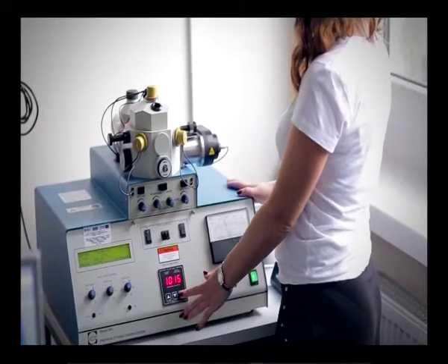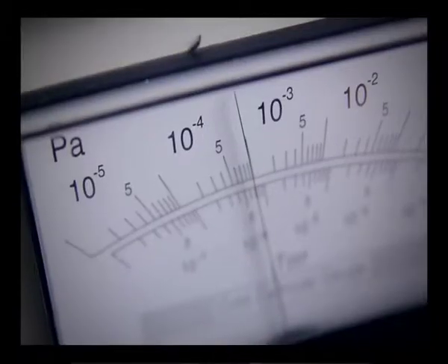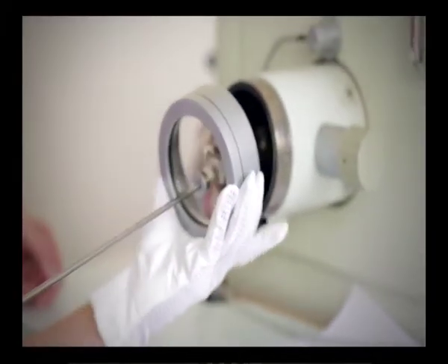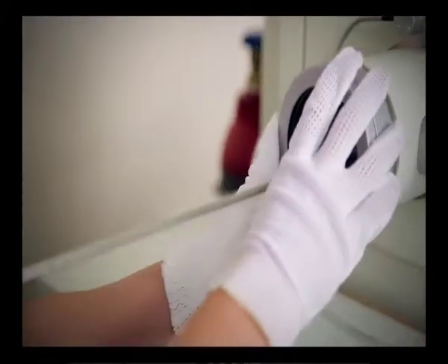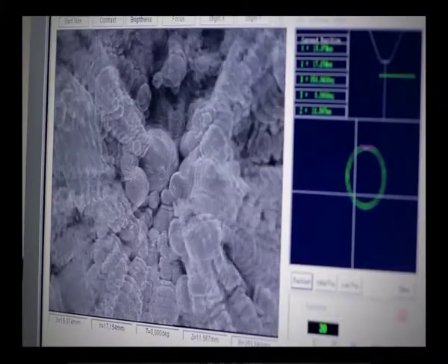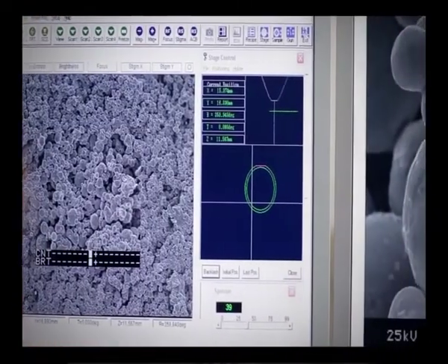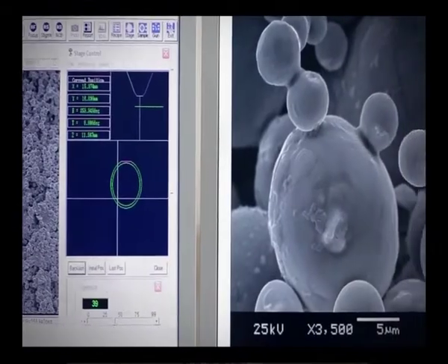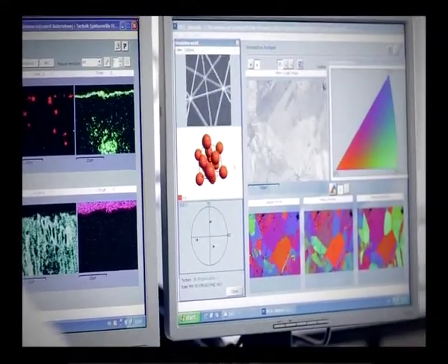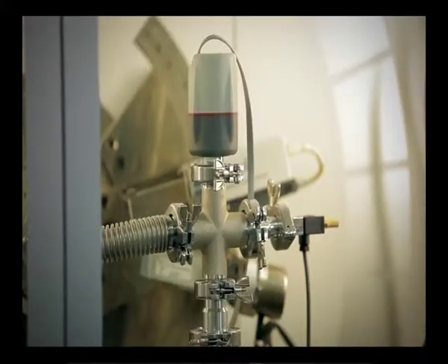The microstructure of the food materials is particularly relevant to drying, as both liquid water and water vapor move within the structure. The microstructure, as far as the transport of heat and chemical species is concerned, is mainly made up of compounds such as protein, fat, carbohydrate, minerals and air. Porosity and tortuosity are usual characteristics. The material's composition and its affinity to water play a key role in water holding capacity and local evaporation rates.